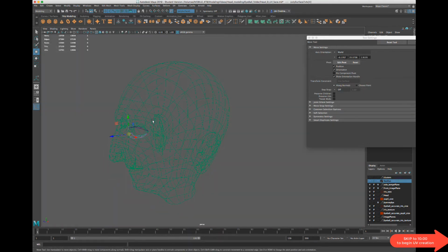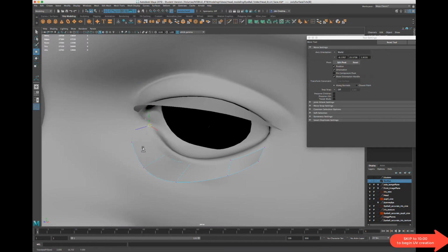So when you select the head and select Modify, Make Live, the head mesh becomes this green color. It means it's ready to draw upon. It kind of makes a magnet out of it, so anything you're drawing on it will stick to it. And it's a great way to sculpt something that's form-fitting around the contours of it. So it's kind of cool to have if you want to rethink how any of the parts that might be separate. And this will definitely come into play if you're making hair cards on the top of the head. So again, that's Make Live.